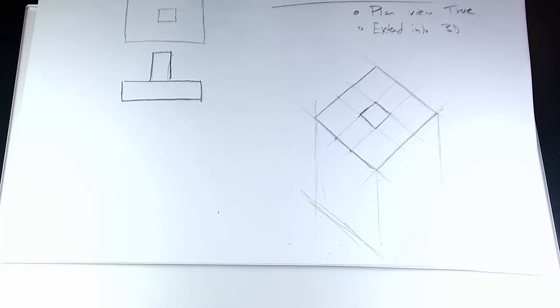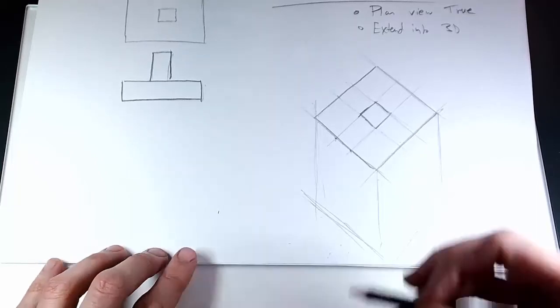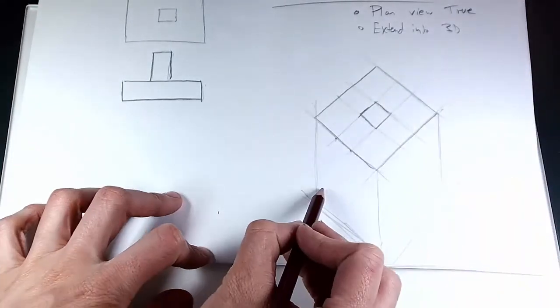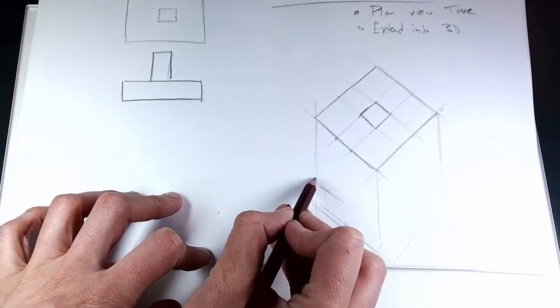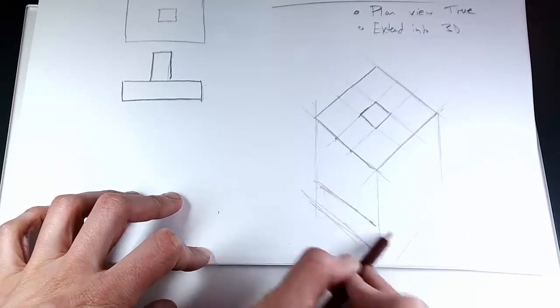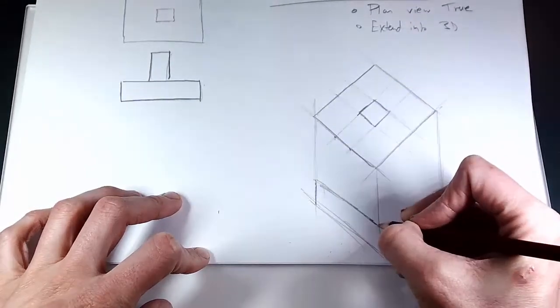What I can then do is project the side view onto each side of that cube. So that I've got a plan view on top, and I'm going to draw the side elevation on this face and on this face, because it's the same for both, for this particular one. But it has to be angled now because my face is also angled, the viewing face is also angled.